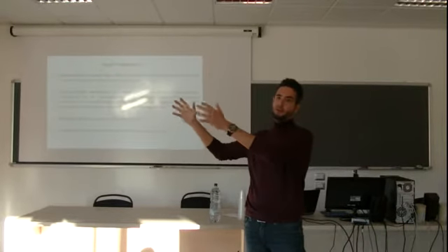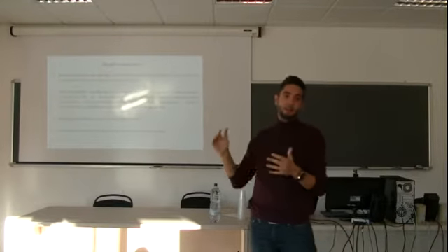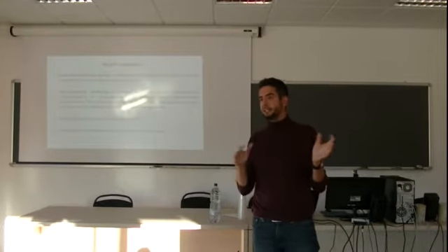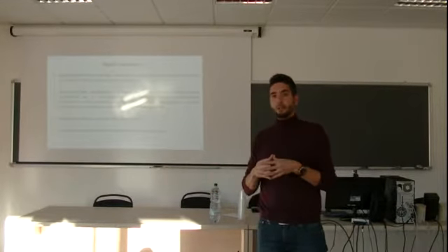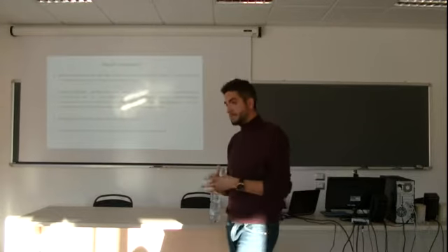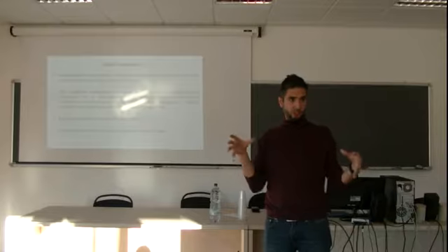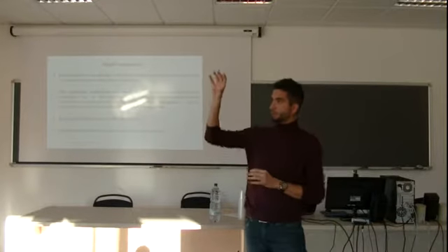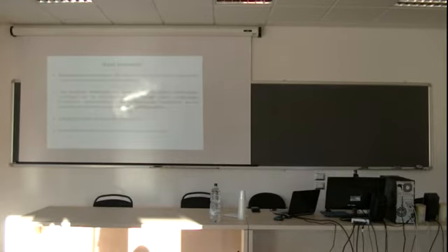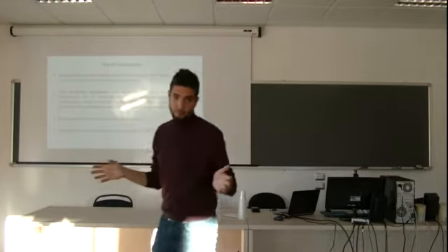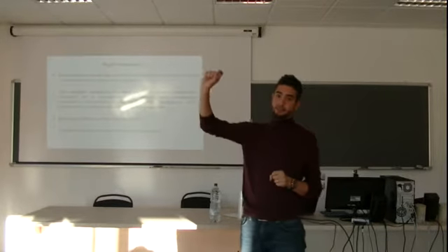How do we know it? It's very difficult to find experimentally which is the best shape to minimize consumption of heating and cooling during the whole year, here in this room, for example. One thing we can do is develop a numerical tool simulating the thermal performance of this room, and then we take variable A, which can be height, and variable B, which can be width of the window. Then we can optimize variables A and B.